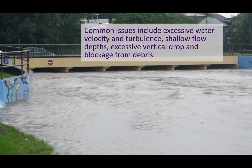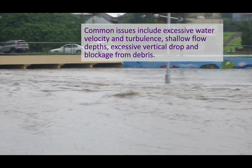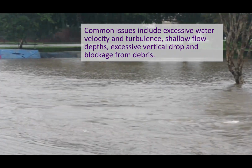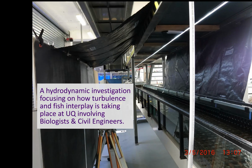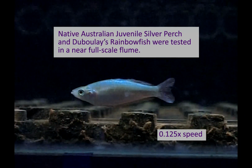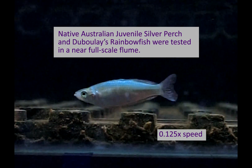Common issues for fish swimming through culverts include excessive water velocity and turbulence, shallow flow depths, excessive vertical drop, and blockage from debris. A hydrodynamic investigation focusing on how turbulence and fish interplay is taking place at UQ involving both civil engineers and biologists. Native Australian juvenile silver perch and Duboulay's rainbowfish were selected to be tested in near full-scale conditions.